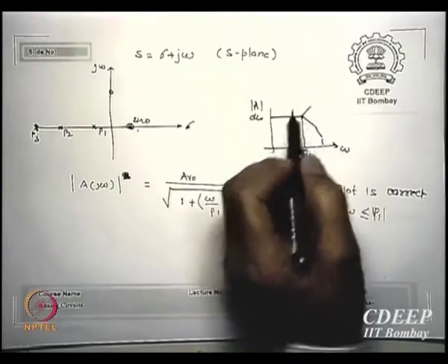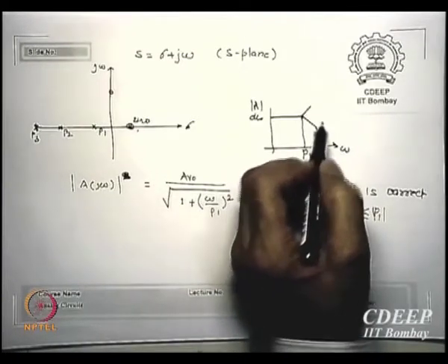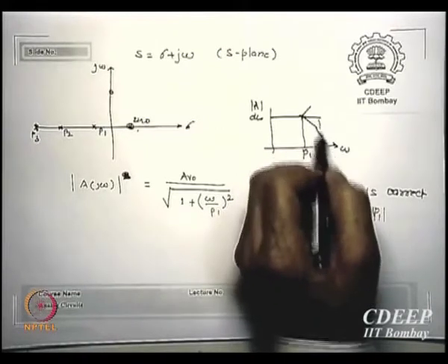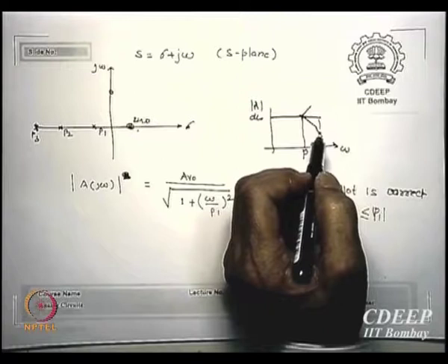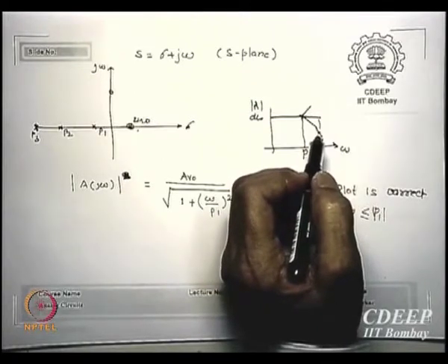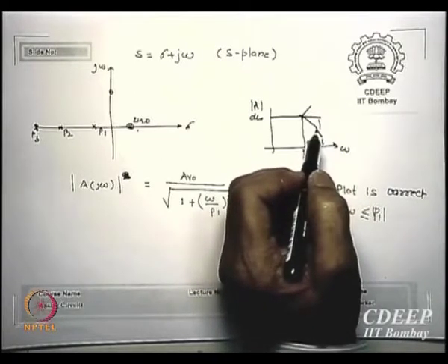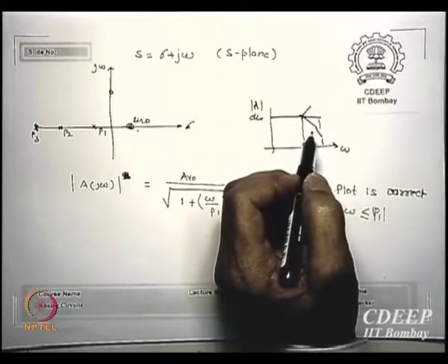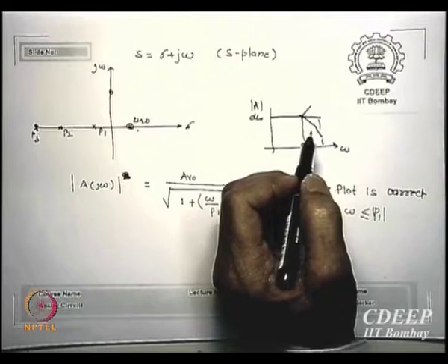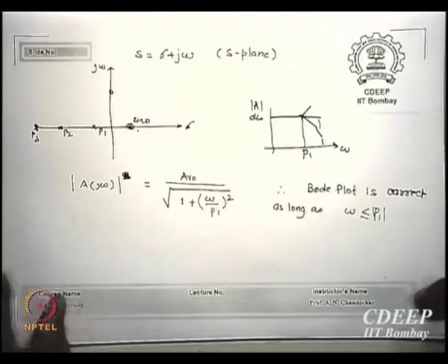If I put a zero here, what will happen? Till the next pole occurs, which then will become dominant, the gain may become higher. But something else I have given up by that, and we will see what happens in feedback, we will use this theory. Oh, I nullified that, but I lost something else, okay. I increased bandwidth definitely, okay. Is that clear? So I must be losing something in getting higher bandwidth, okay. So we will see what exactly we lost, is that okay? We will see that a little later. So is that issue clear?